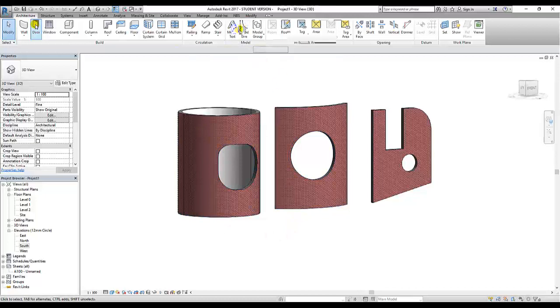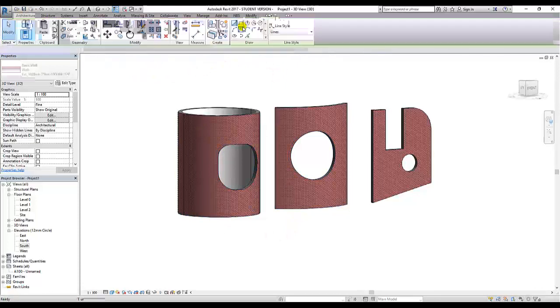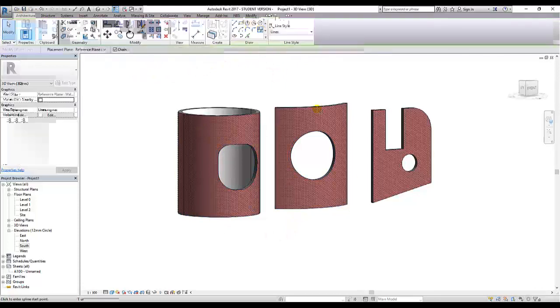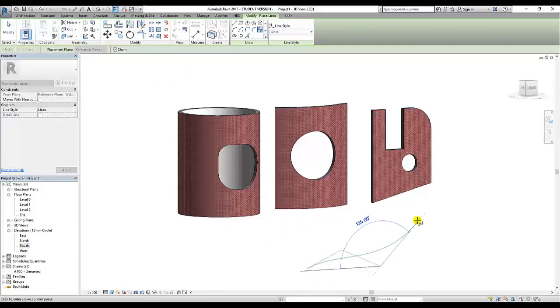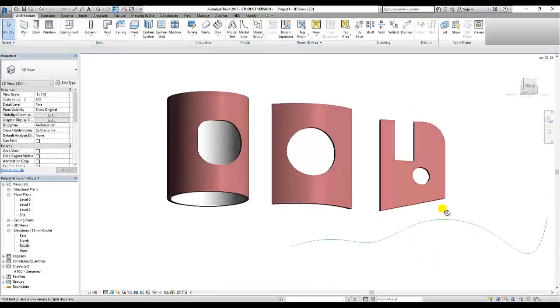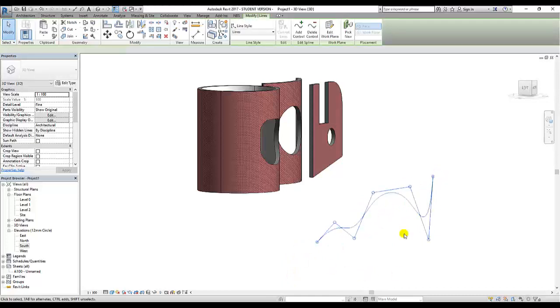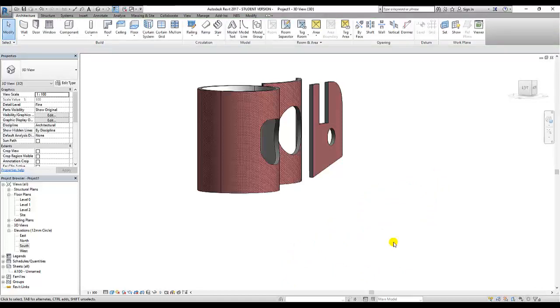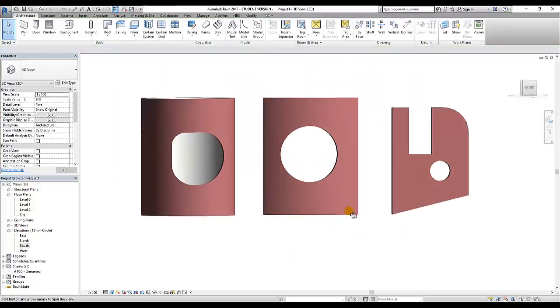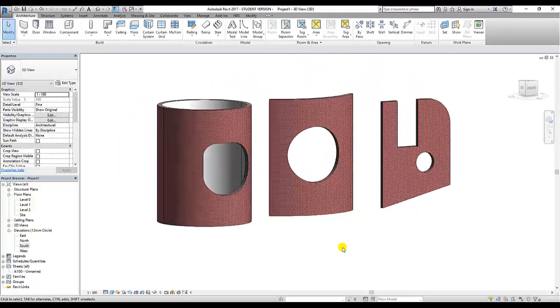all these sorts of things in class. But if I wanted to create a spline, which I can do with a model line, this function. So you might want to create something a bit more creative. Okay, that's still on that surface plane. I can't use the wall tool to map to that, but I can create a wall following this shape using a different method, and I'll leave that for another video. Okay, so that's it for now. Have fun making strange holes in curved shapes.